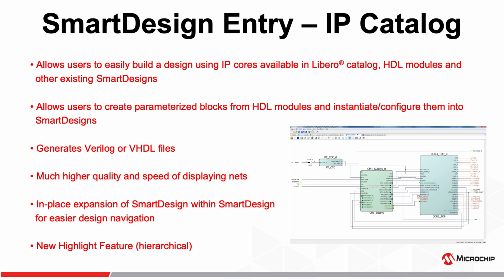The one important point which I would like to highlight here is the in-place expansion of the SmartDesign within SmartDesign. Basically you have a plus mark here. This is the top SmartDesign, one of the top SmartDesign blocks. If you click on this plus mark, inside that you have sub SmartDesign components. You can completely see the hierarchical view of all the sub SmartDesign components once you click on this plus mark. I will show that in the demo.